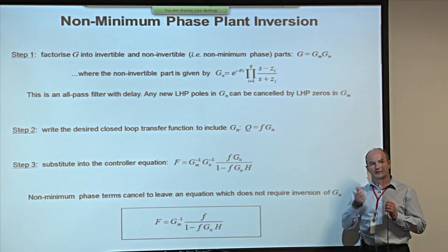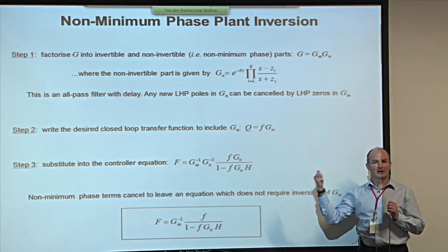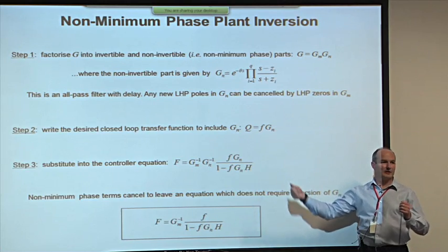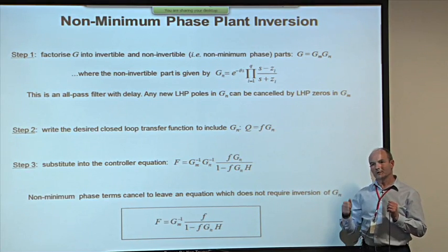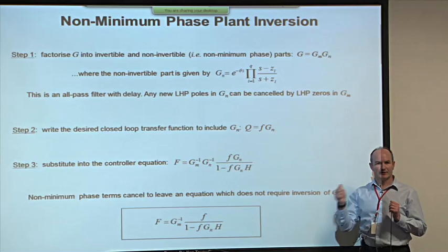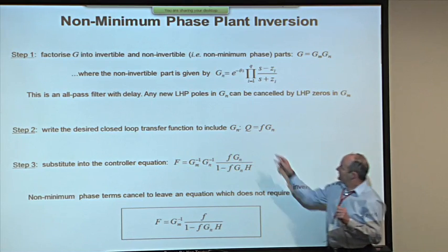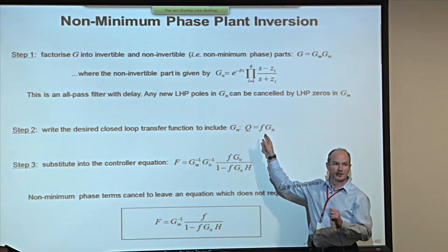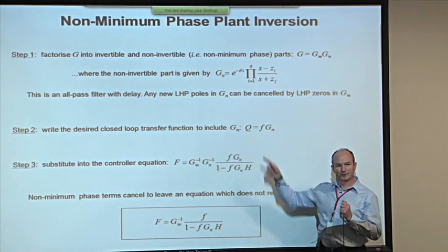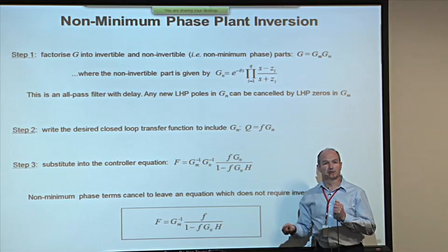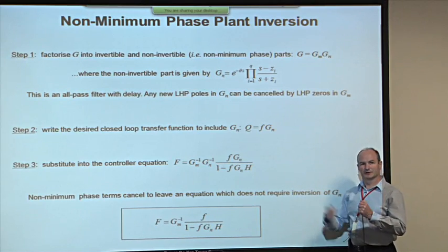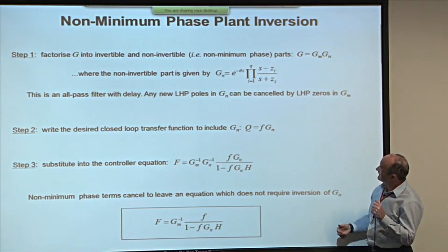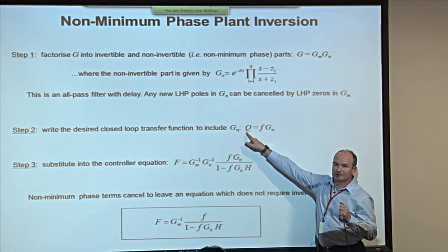Instead of trying to invert this to give us the arbitrary closed loop response we want, what we do is we choose the closed loop response we want so that it includes the non-minimum phase part that we can't invert. And then we calculate it and we pretend that's what we wanted all along, you see. It's like fiddling the question to suit the answer. But anyway, it works. Because now, when you substitute G...